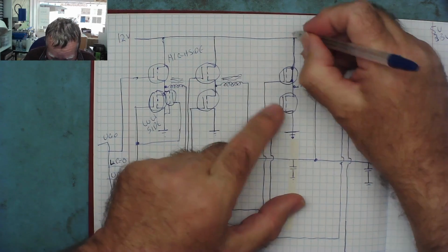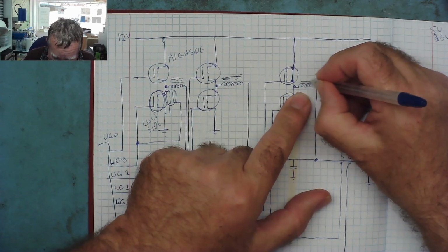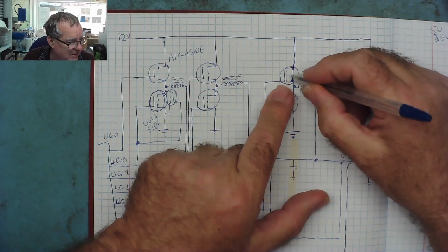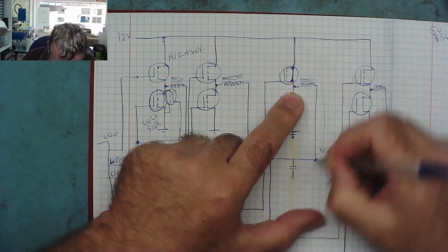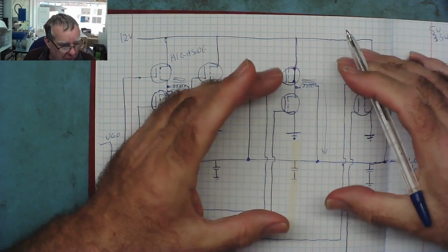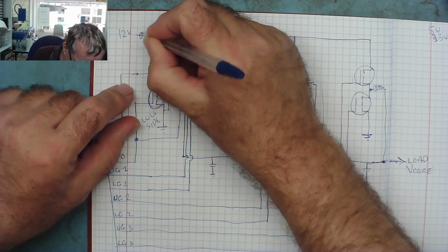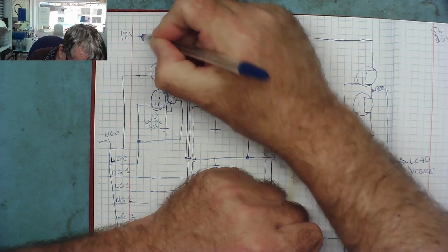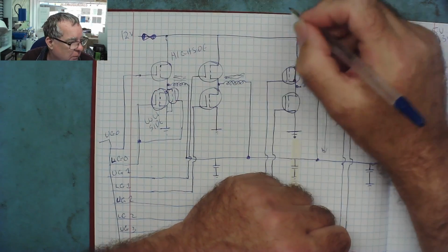So when you power up, all the 12 volts comes down through here. In the first few microseconds it will magnetize the coil. As soon as the coil is fully magnetized, this can't turn off, so the current now goes down here into these capacitors, into the load, and this will draw a massive current. If there's a fuse in the 12 volts, which there often is on higher end graphics cards, but not always, the fuse will blow.